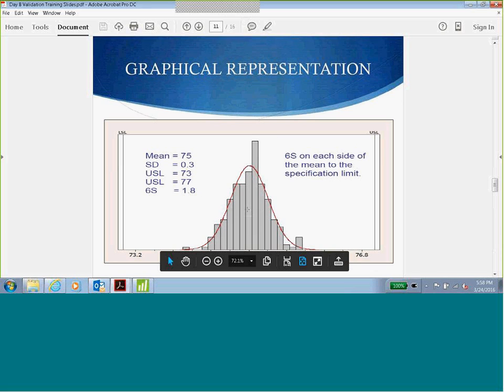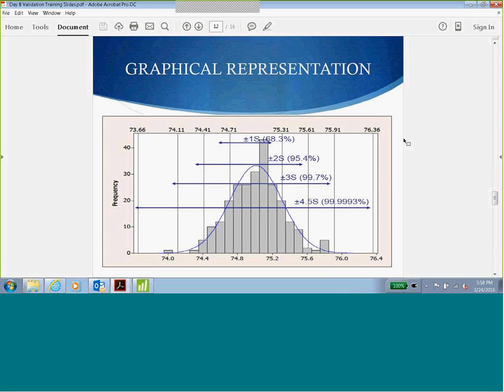You got all the samples, you have shown each and every sample, and you got your mean, and from the mean you will be calculating your variance and standard deviation. And 6 sigma, also called 6 standard deviation, has become an industry standard. The process should be within 6 standard deviations, in the sense that most of the requirement is that all manufacturing processes should be within 6 standard deviations. That is what 6 sigma represents. From the center axis, plus 3 on the right-hand side and minus 3 on the left-hand side, so 6 sigma is plus or minus 3 standard deviations. The slide will have accurate information of what I said.